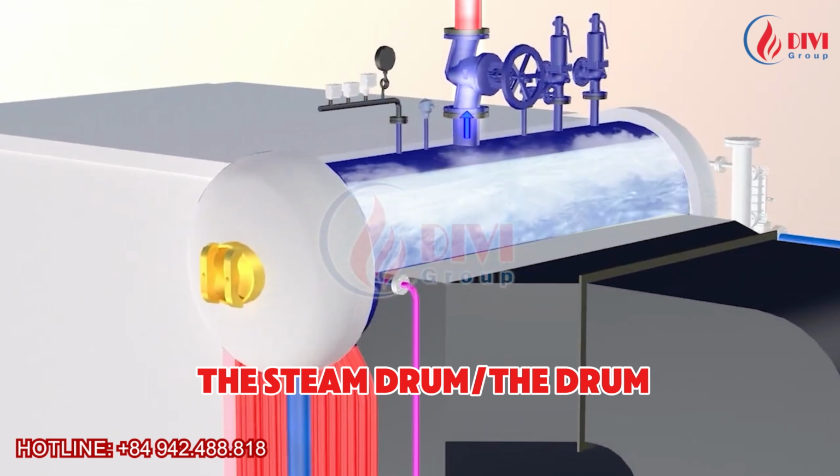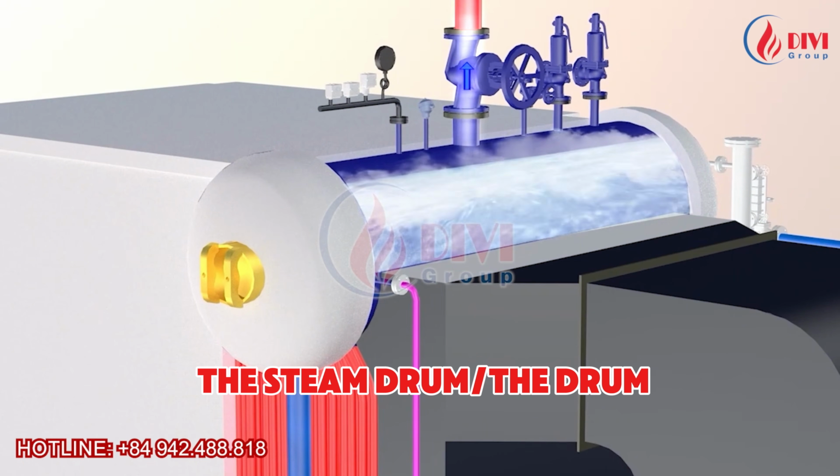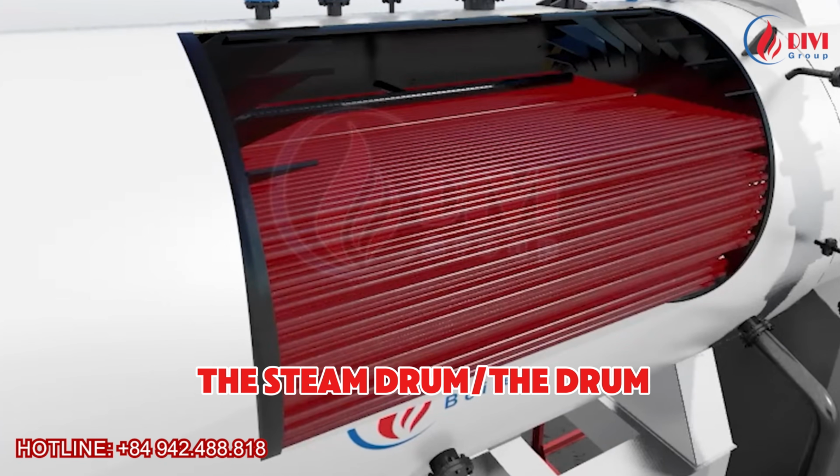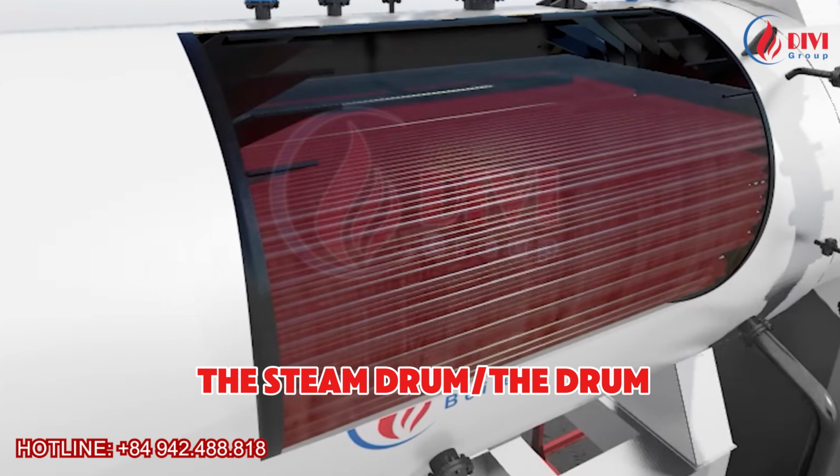The fourth term is the steam drum, sometimes simply called the drum. A steam drum is a large cylindrical vessel that contains both water and steam, or only water, depending on the boiler design. The drum separates steam from water, stores a certain amount of steam, and helps stabilize the steam supply.